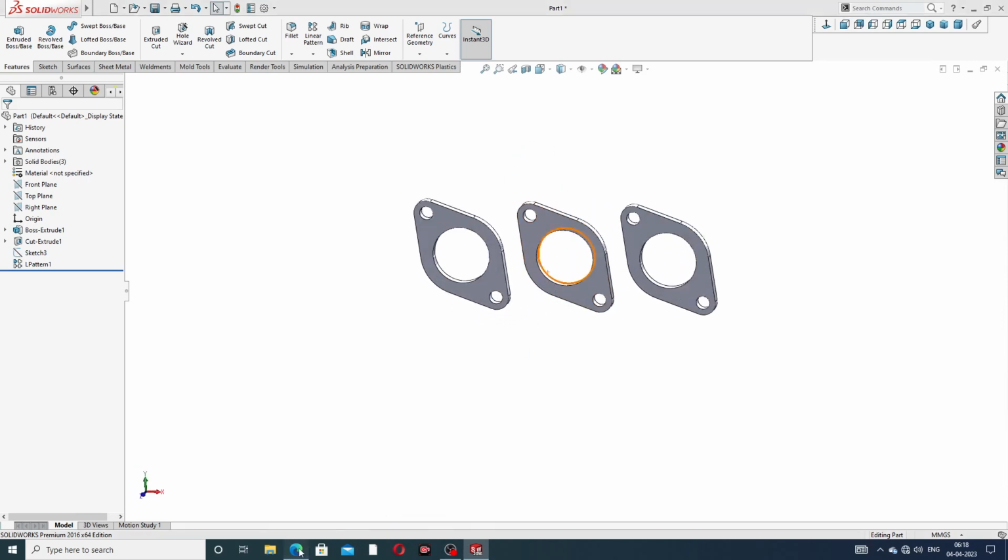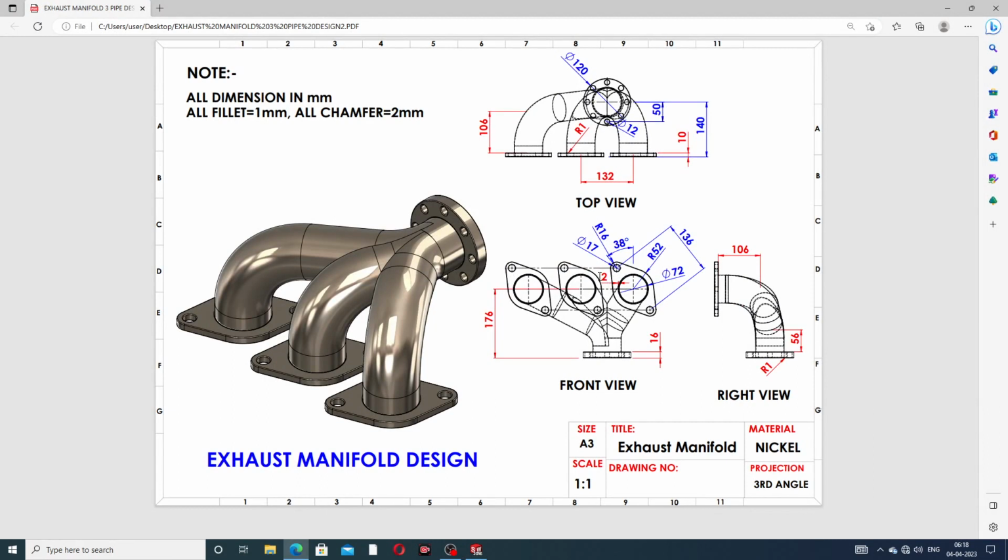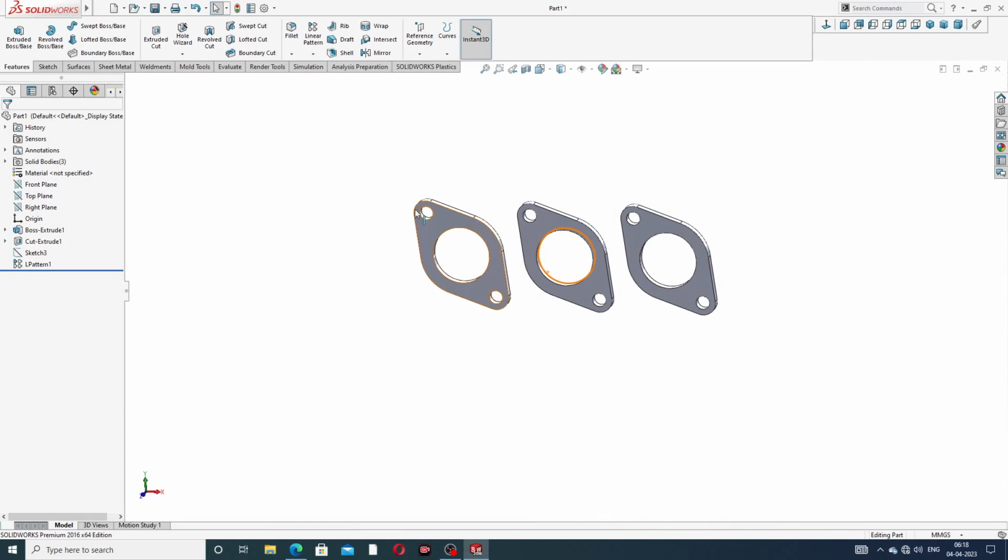Okay, next point is correct, and next point is drawing this body, the 176 millimeter. Use the top plane and use this body. This big circle is 120 millimeter, and this point to this distance is 50 millimeter, correct, and this point to this distance is 140 millimeter, is perfect. Okay, all is correct. And this small circle is 12 millimeter.